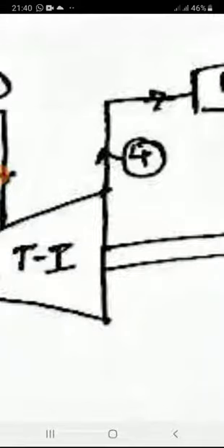and combustion takes place. And after the combustion, the temperature of air will be increased and the air will be converted to combusted gases. The combusted gases will pass to the high pressure turbine, where they get expanded to a lower pressure, which is 2.24 bar. Intermediate pressure is given as 2.24 bar and a lower temperature, right?